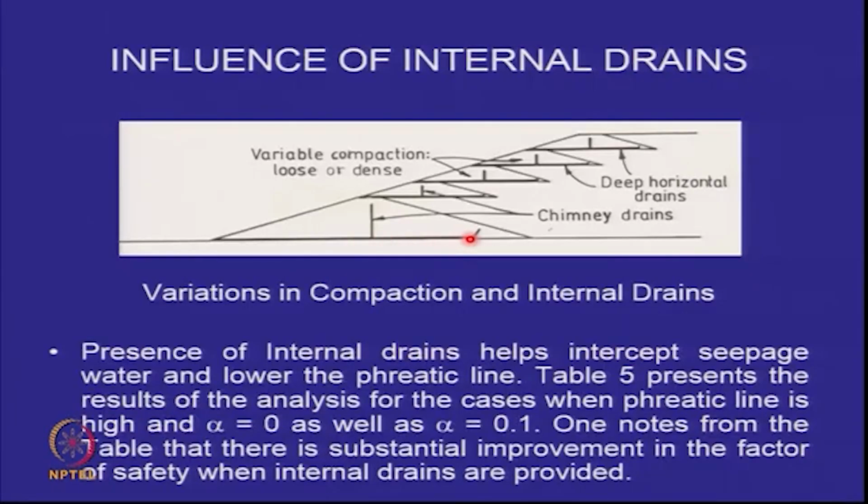However, there is a danger. If you take this very deep and there is water here, the seepage levels will be higher. You will get more water out of the pond because it is very close to the upstream slope.